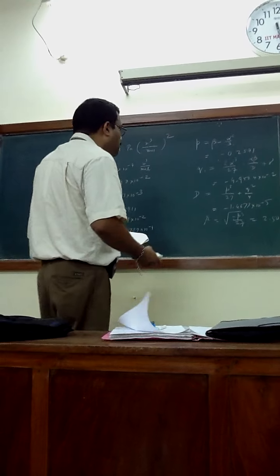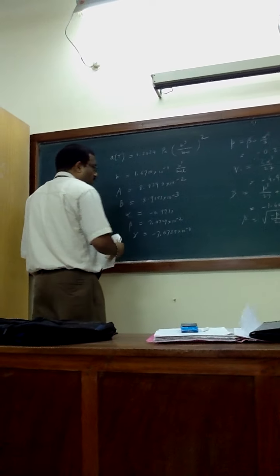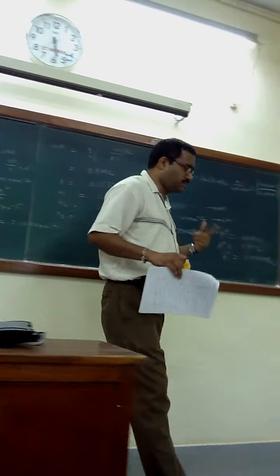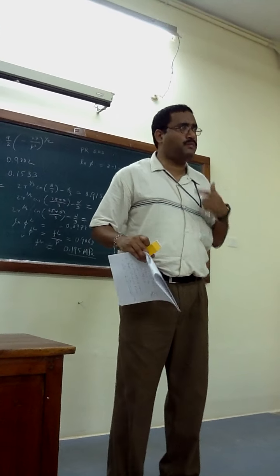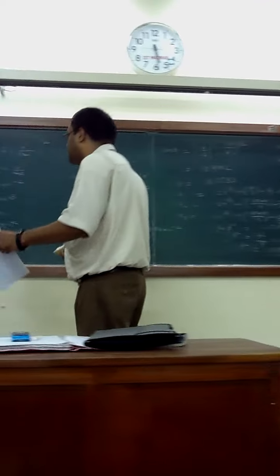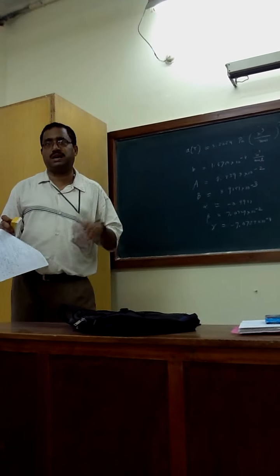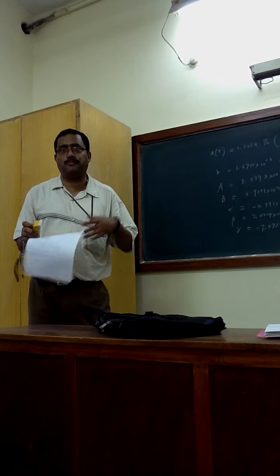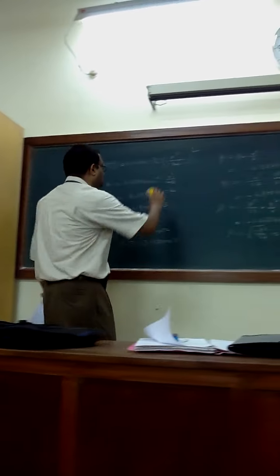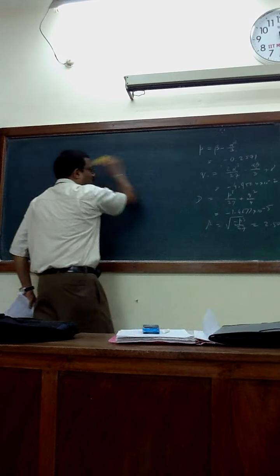Okay, and proceed further. Generally, when we started, we took the system pressure as 0.215 megapascal. Then you are saying the system pressure itself is the saturation pressure. But we are seeing that that assumption itself is wrong. So you have to go for the new system pressure, which will be your saturation pressure.